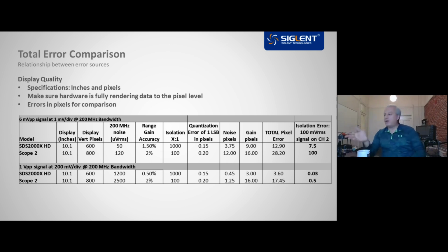So worth noting here that when we add the isolation, we add another signal into this mix, which can be a major issue when looking especially at the smaller signals. So without good isolation, that impact from adjacent channels can really dwarf all the other errors within the system. Typically on your higher level signals, it's not as big of a problem.